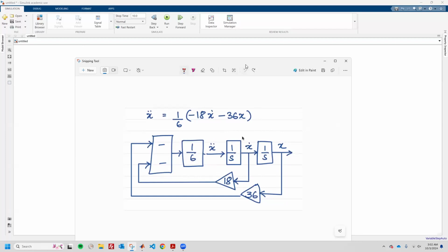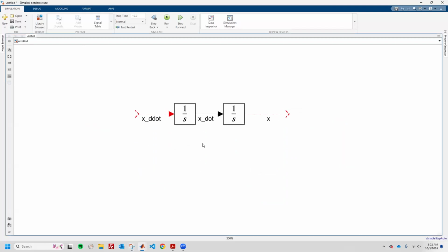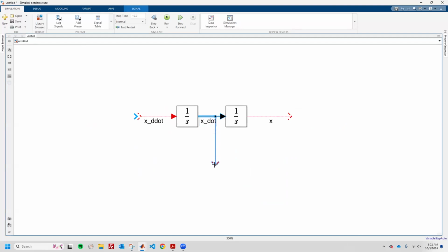And now we want to build the rest of it. There's no particular order in which you need to do this, but the thing that you have to keep in mind is if you want to create a copy of a signal, you move your mouse there and then you right click, hold, and pull. Okay. So now you've created a pickup point or a takeoff point. I just hit Control Z and it deleted the whole thing. So I hit it again and now it's back.